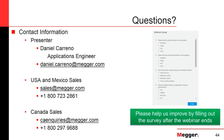Yep. Here are some questions from the audience. So does the ohm meter you choose have to be able to reach the rated voltage of the transformer in order for it to perform the test correctly? No, the voltage of the transformer does not come into the picture for that testing. You just need to be sure that the tester that you choose is meant for transformer resistance testing. And usually the difference is the open circuit voltage in the tester is bigger to be able to saturate the windings and get stable readings.